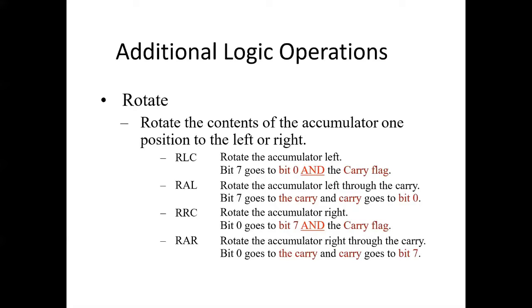We have to note that the carry flag is not involved in the rotation, and it is only an 8-bit rotation of accumulator contents. Only carry flag is affected by this instruction execution. This instruction is useful to check the value of LS bit of accumulator and perform a rotate right. It is also used to perform division by 2. It works correctly for unsigned numbers as long as the LS bit of accumulator is a 0 before a rotation.